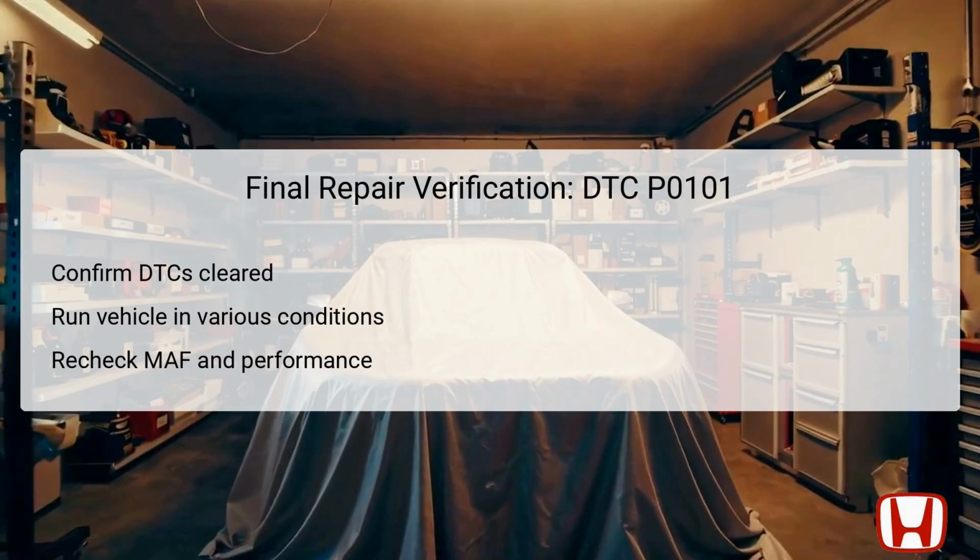As we conclude the troubleshooting process for DTC P0101, it's essential to verify that all repairs performed successfully addressed the issue at hand. Begin by confirming that all diagnostic trouble codes have been cleared from the vehicle's onboard computer, as this resets the system and can provide a fresh start for performance evaluation.